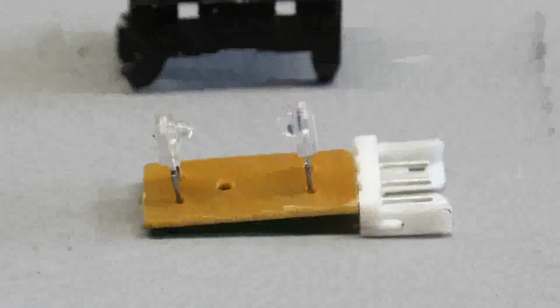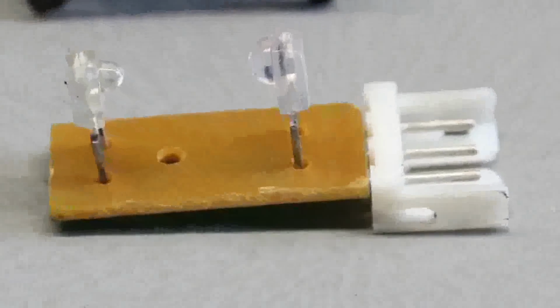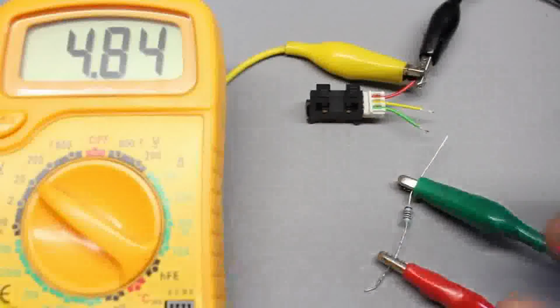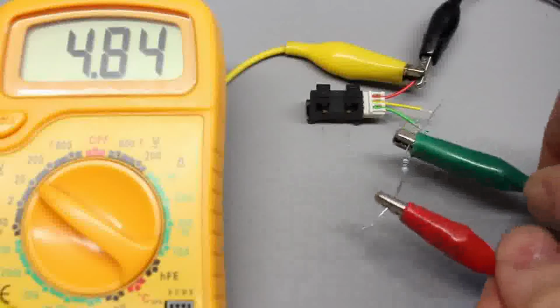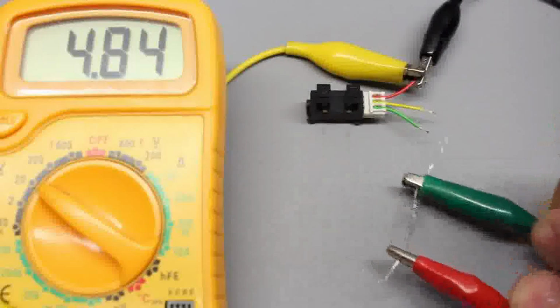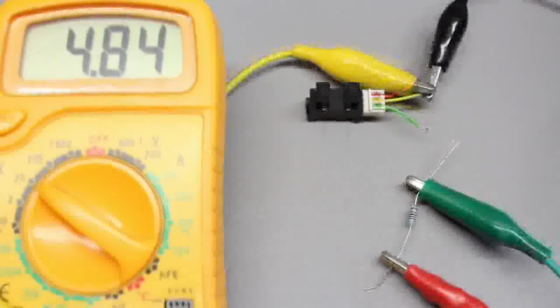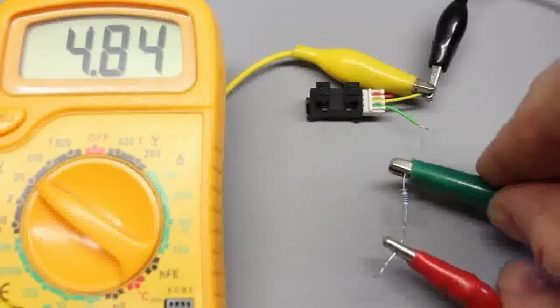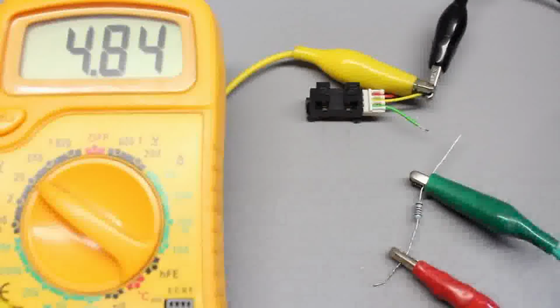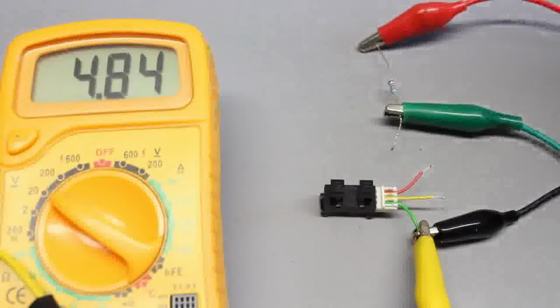In an old printer I found several optical sensors having just 3 terminals. We can identify the configuration of the terminals using the same method as before. Connect the optical sensor to the 5V line through the 12 kiloohm series resistor using all combinations possible while recording the voltage across the terminals of the device.